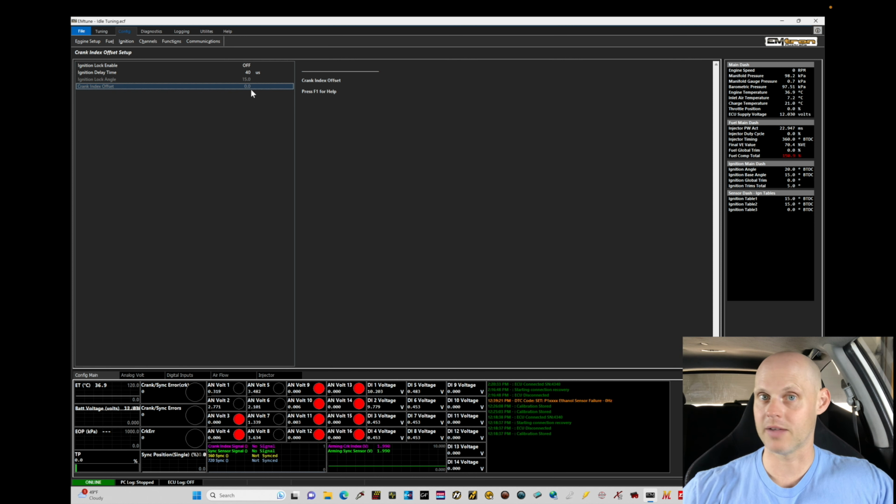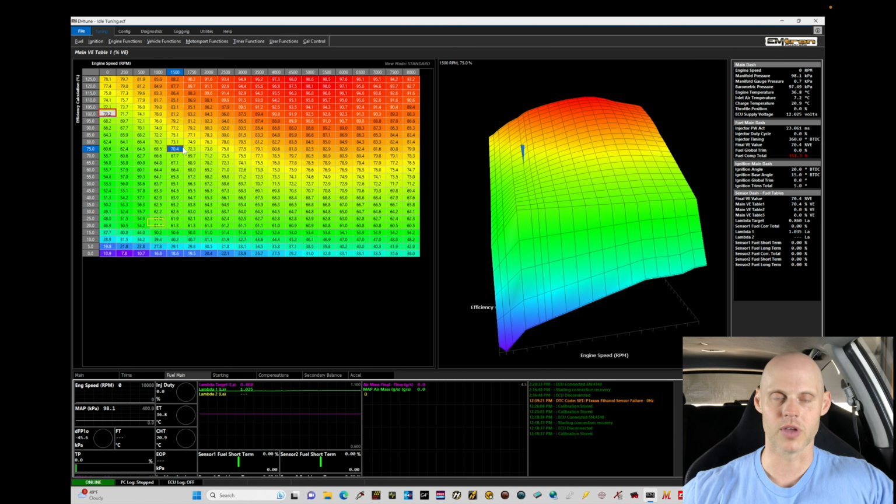So that's what I wanted to just mention here as we're coming into this tutorial. Let's go back into tuning and let's talk about a few things. Now, what we're going to be doing here, very first thing, is taking a look at doing our fuel tuning. And fuel tuning, I am going to be simply referring to our VE table, or air mass tuning.